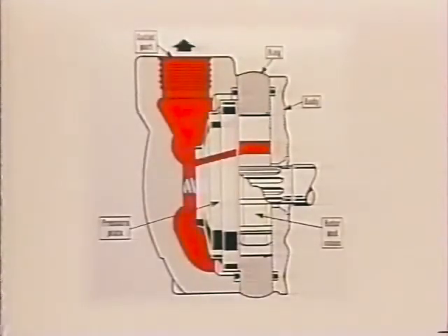In this pump, the rotor and vanes are held against the machined surface of the body by a spring-loaded pressure plate. The outlet port is in the pump cover, enabling outlet pressure to assist the spring in holding the pressure plate firmly in position. The square cover permits the outlet port to be assembled in any of four positions in relation to the inlet, which is in the body. This, of course, simplifies piping during pump installation.